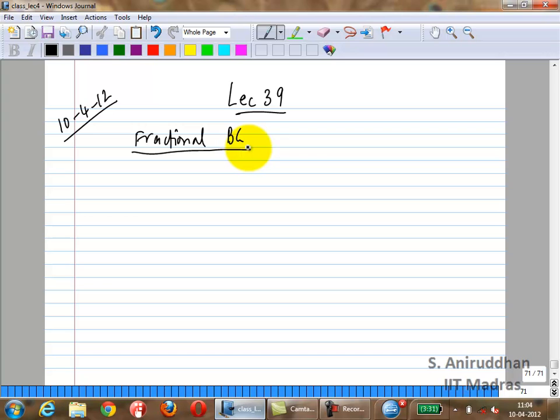So far all the bandgaps we have looked at, at least the ones we looked at in class, had an output voltage of somewhere around 1.2 volts. Now what do you do if your power supply becomes less than 1.2 volts? Let's say your power supply was only 1 volt. What would you do? You obviously have a problem, because you expect all your op amps, all your circuits to operate at some particular voltage, at VDD, and if that VDD itself becomes smaller, it becomes a problem.